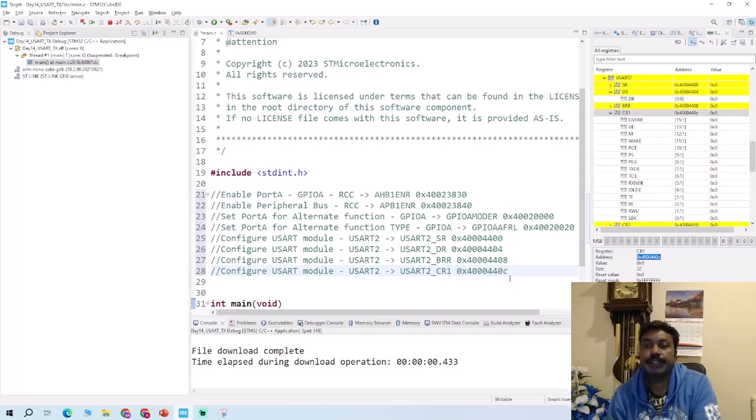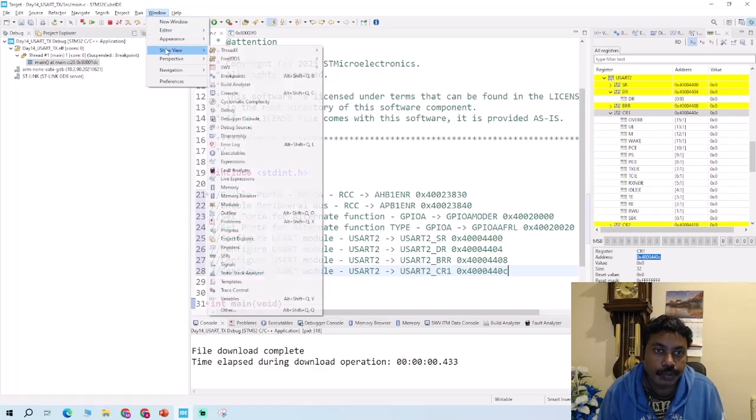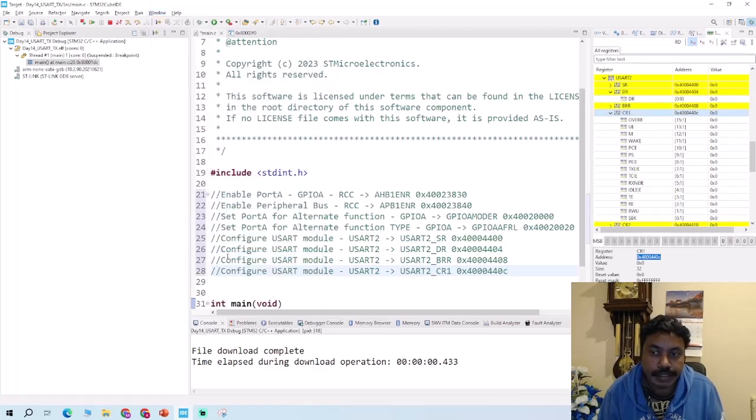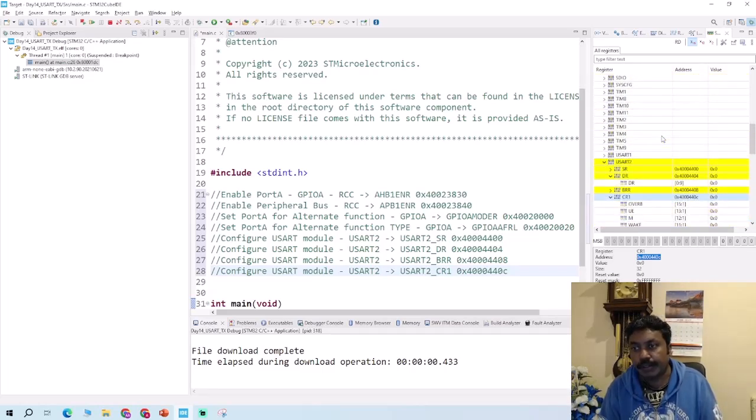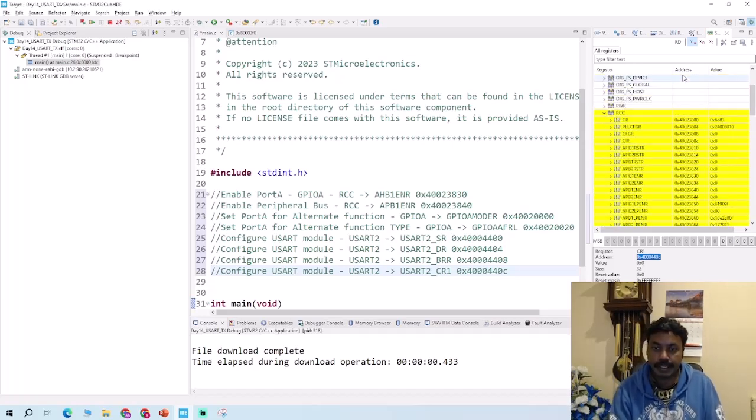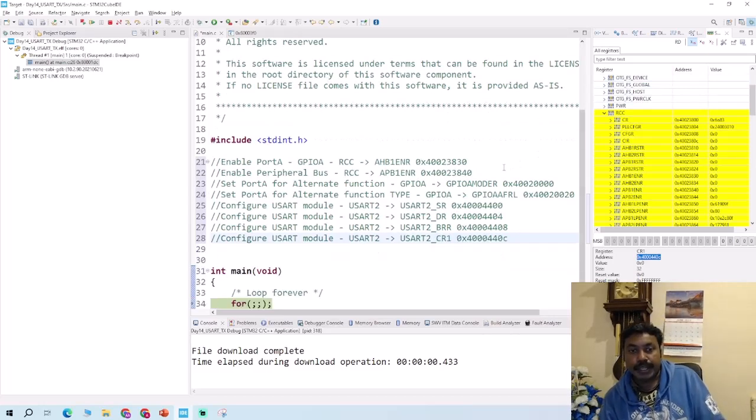Okay, so it is a very good practice. Once you know which register, which bus and which peripherals it's all linking and going to interface with your microcontroller, the good easy way is coming here, going to Window, Show View, and clicking on SFRs. This is what you get, and you get all the registers that you're going to program with, and you're going to write a program to locate the address. So that's really key. So now we did the easy bit.